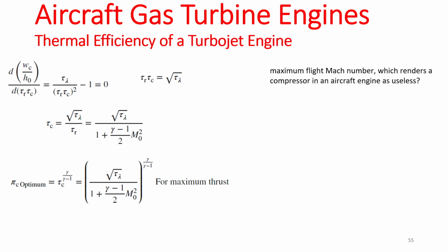It's a little less compressed. Your performance may take a hit. You're going to have a smaller thrust, but it's not going to change the flight, right? So the parameter that you're going to have is pressure ratio of 1, right? As you get closer to it, you can just turn off the compressor. Or, I mean, there are mechanisms that change from the non-ramjet to ramjet, right?